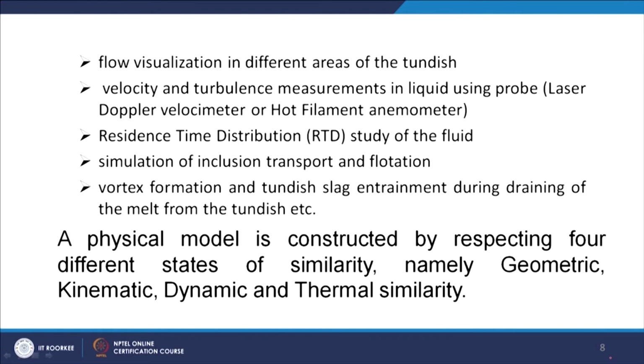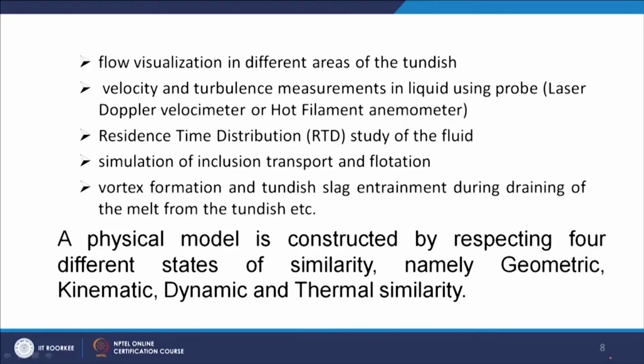You can do the RTD study of the fluid. RTD is the residence time distribution study. Basically we do that by tracer dispersion studies, and by that you can get a feel of the time for which an individual fluid particle stays, or on average what the stay time of the fluid inside the tundish will be. That is your residence time distribution. You can have that at different points inside the tundish.